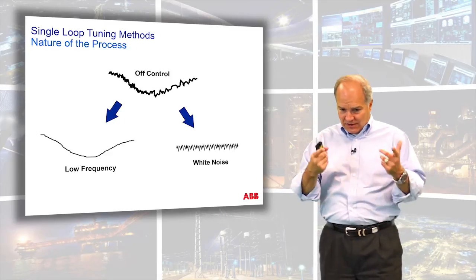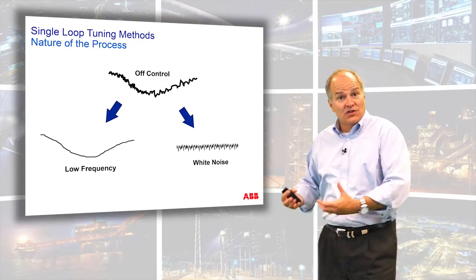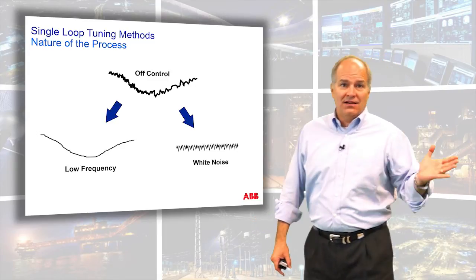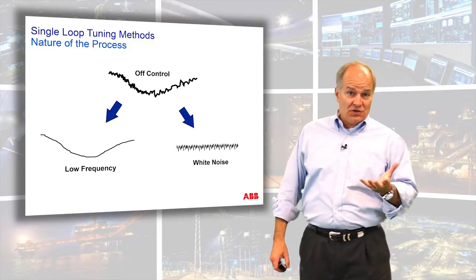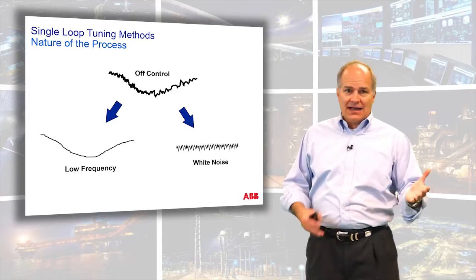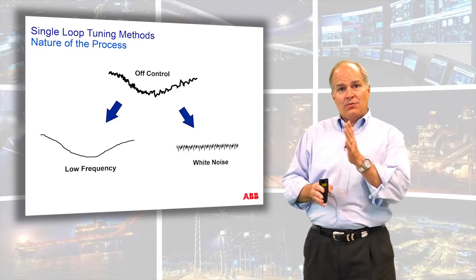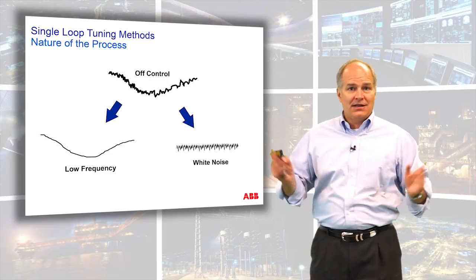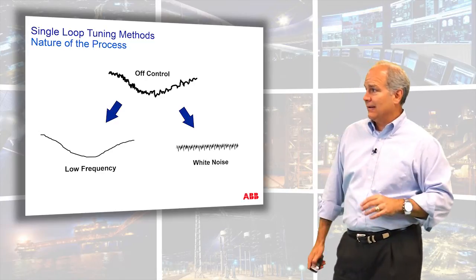It has to look at that disturbance, reflect it into the actuation device, like the shock absorber, and try to reduce the intensity of that disturbance as it moves through. One of the benefits, a huge benefit of the direct synthesis tau ratio tuning that we talked about, is you can actually calculate the point at which, in the frequency world, a controller's ability to regulate stops or gets tremendously attenuated, and we're going to look at that.